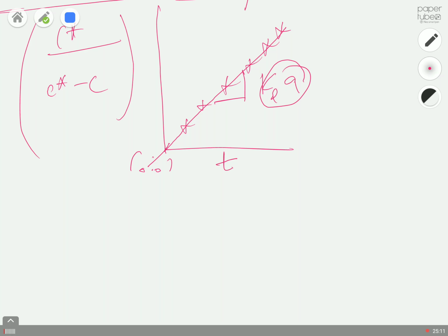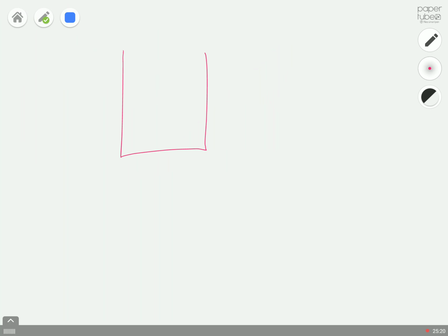And how do they get this value in the lab? So in the lab, they take a reactor and fill it with a fermentation broth, or normally they use water, for example. They just want to know how much oxygen they need to supply, or how to achieve the conditions at which the mass transfer rate will be maximum. So they put in an impeller and start to agitate, say at 400 rpm.